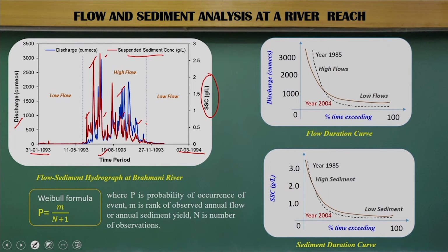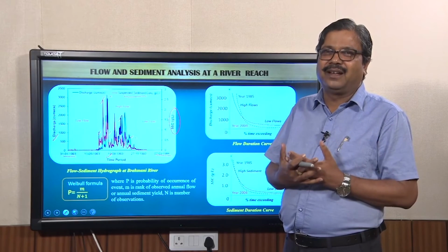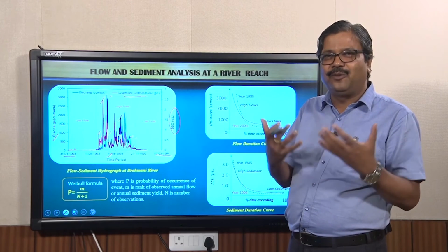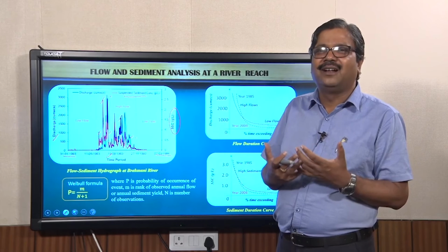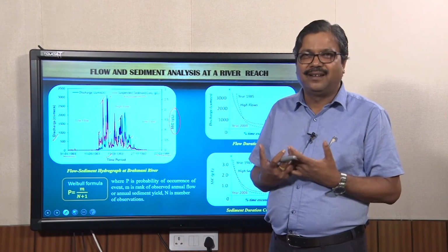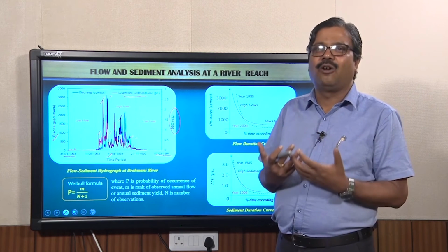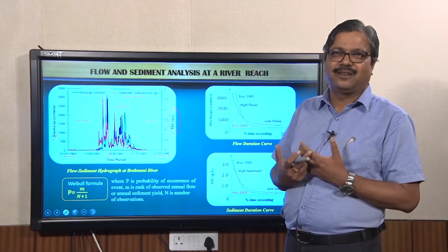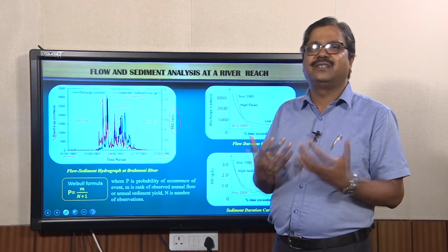Like many times when you go to a doctor, you go for X-ray reports. Similarly, whenever we start any river engineering project, we first look at how the flow variability is and how the sediment variability is. First we draw the flow hydrograph and sediment hydrograph, because that explains how the river behaves.